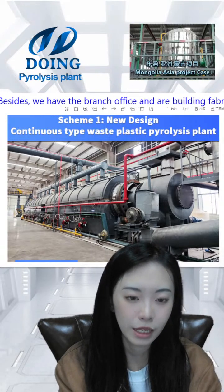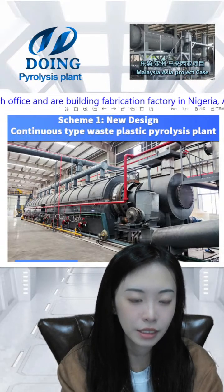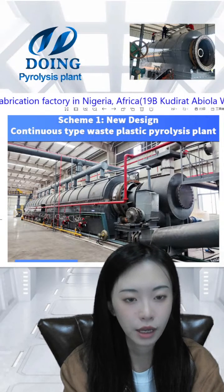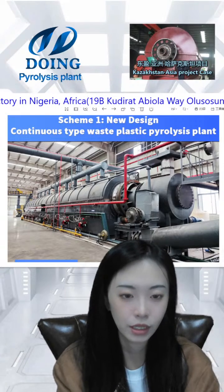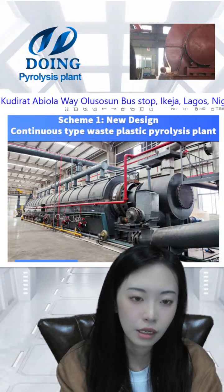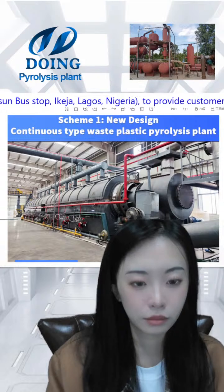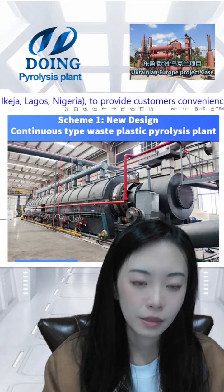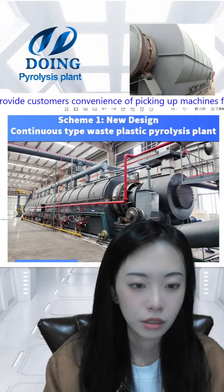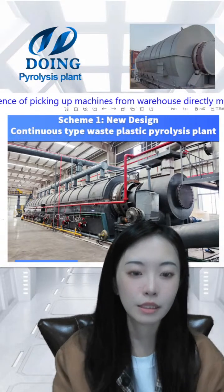If your plastic has a lot of PET and PVC inside, it's not suitable for this business, because they don't contain much oil and they have a big problem of corrosion. If you have other plastic, like PP and PPS, then it is very suitable and has a high oil yield. If you get pure plastic, the oil yield can reach 90%.